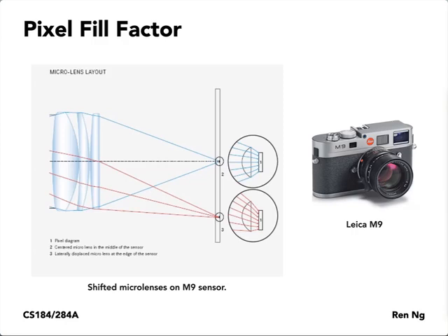And for the microlens, it makes sense for it to be centered directly over the pixel. But if you look at a pixel that's off near the corner of the chip, it's not quite that way anymore, because the rays of light that are arriving there arrive at these oblique angles, as you can see, right? Because it's not centered along the optical axis. So if you figure the optical design out, you want the lens to actually be displaced a little bit upward in this case to catch this total set of red rays and direct them more optimally towards the center of that photodiode area.